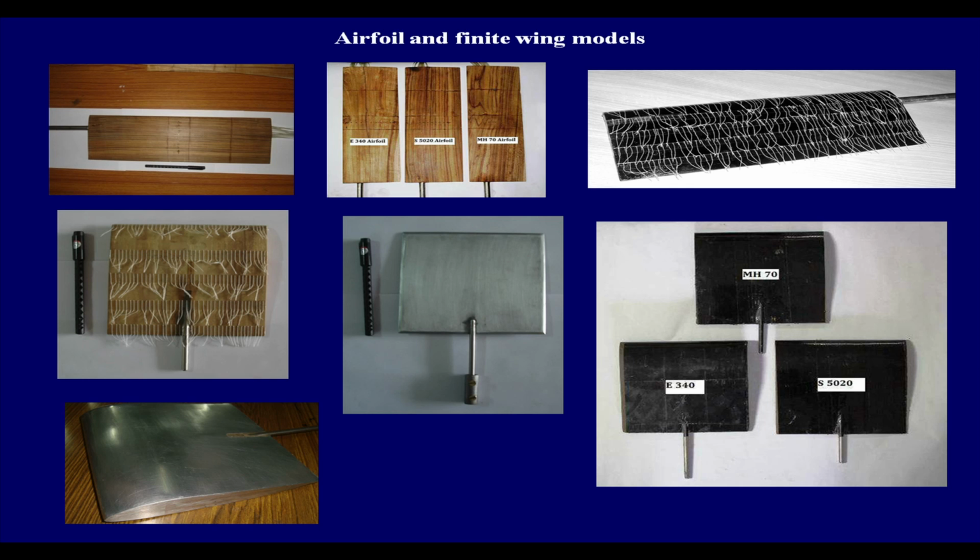For example, if you are in an industry where you have to do regular measurements on, say, scaled down aircraft models and things like that, what do you look for? You always say that I would not intend to use a very highly scaled down model, because I am sure there would be major scale effects. That is something that we would not like to have. So, that is precisely what we are talking about.